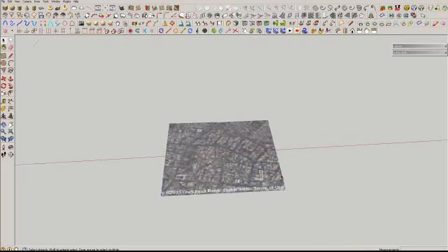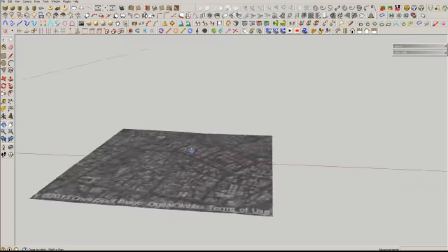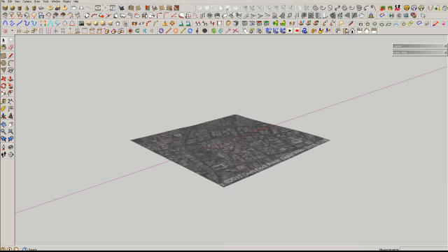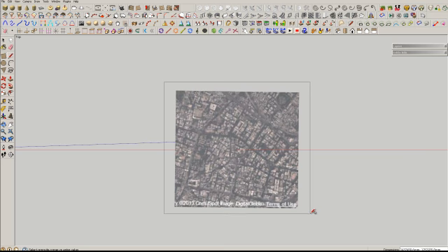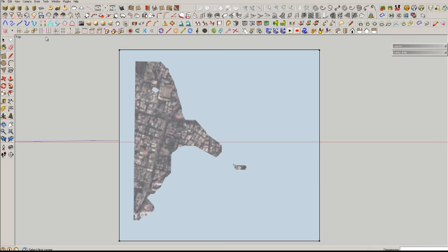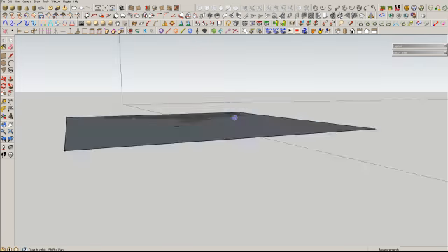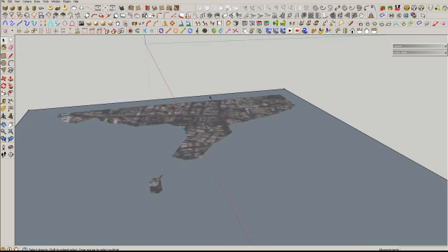Yeah, so let's get on with the contour part of it. What I would like you to do now is go to top view, where's the top view? Yes, sorry, yeah. And then you select the rectangle option. We'll be creating a reference plane like this one. It should be somewhat bigger than the side which you have actually selected. This plane, whatever we have created, actually intersects with the contour surface.